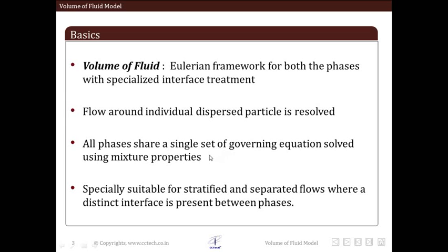Then governing equations are solved for mixture phases and it is shared by all phases. So mixture properties are used to solve governing equations and all phases share a single set of governing equations. This particular model is highly recommended or suitable for stratified or separated flow where a distinct interface is present between different phases.